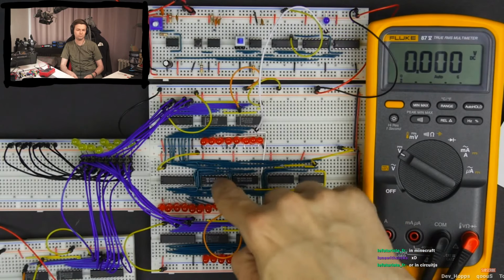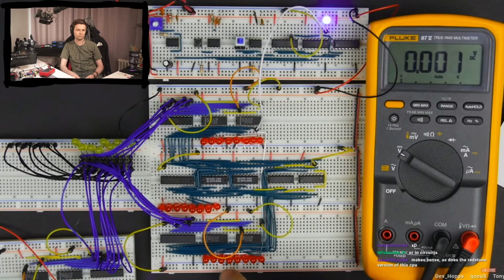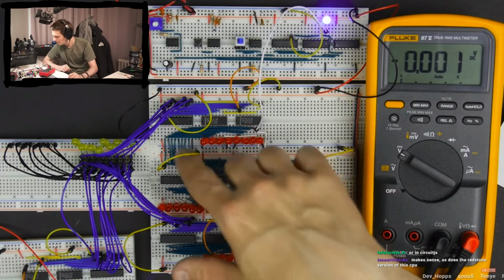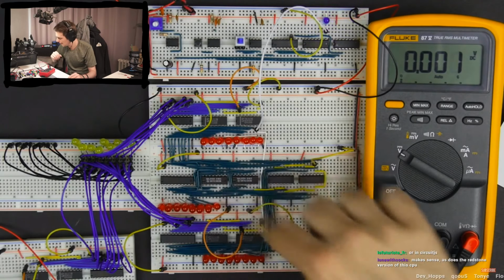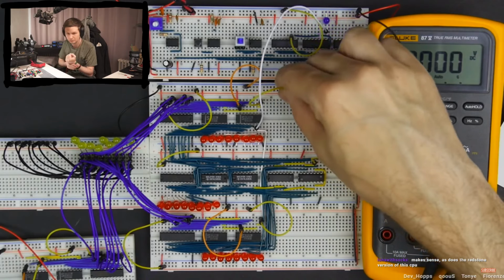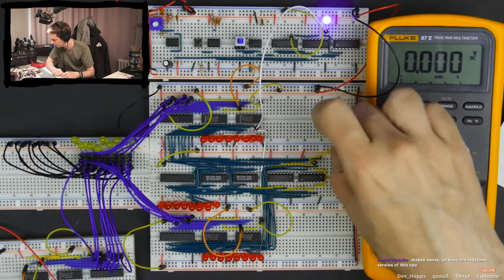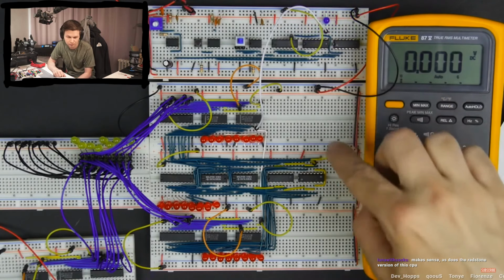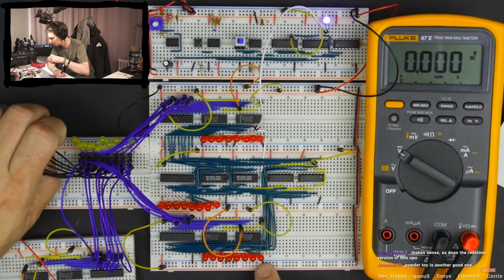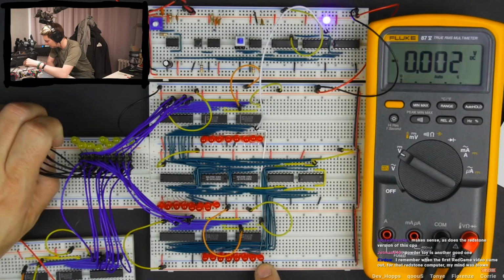I suspect there is still another problem with the B register, because you remember when we started out, the A register was 0, so we wouldn't have encountered this particular problem. So now we can try the same thing with the B register. I will change it so that our B register is loading data from the bus, and then I can manipulate the value on the bus over here to load into the B register.